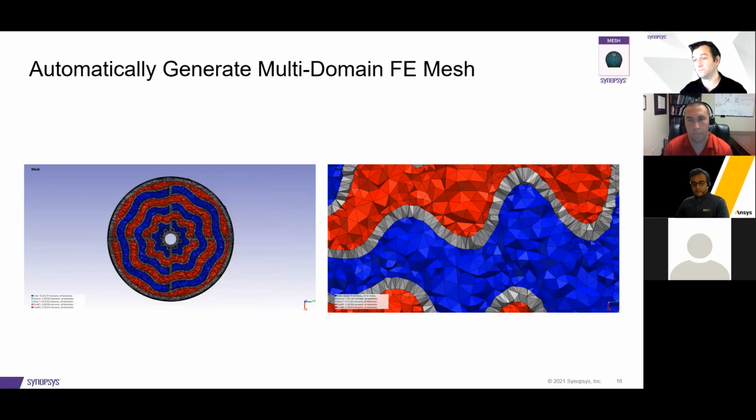And it also will ensure that at all the interfaces, the parts will line up perfectly. There will be no gaps or overlaps, and the nodes of the elements at the interfaces will match up perfectly. These can be specified as either coincident nodes or shared nodes at the interface without any issues. The software also allows you to do some post-processing on these orphan meshes to create node sets that can be used as the basis for specifying loads and boundary conditions in the simulation model.